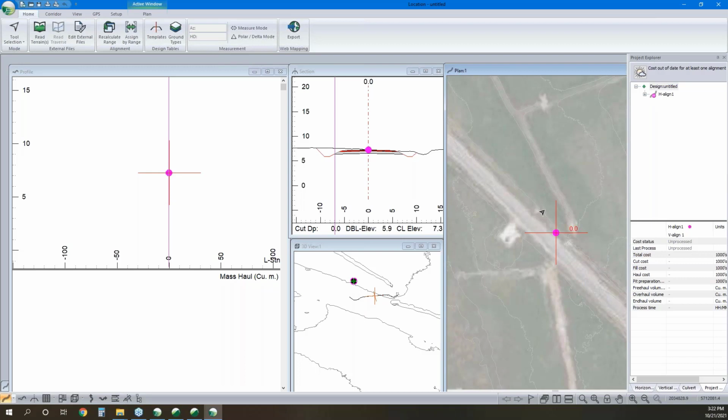So we're going to merge that excavation into our original ground. Of course, it won't be our original ground once we do that merge, and it's happening automatically. And with that, it's going to reduce our design time, and it's also going to keep things dynamic. So if we chose to trench our pipe location at one spot and then something comes up as the project evolves and we move that, well, we can just move a couple points and we're going to see how that impacts our geometry and make the adjustments a lot quicker because it's all happening in the same file and things are dynamic.